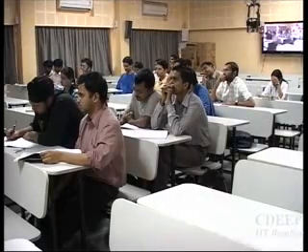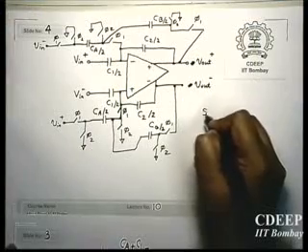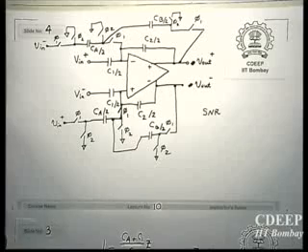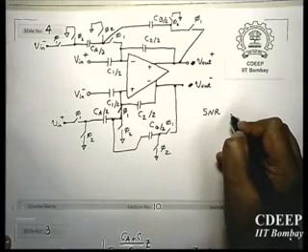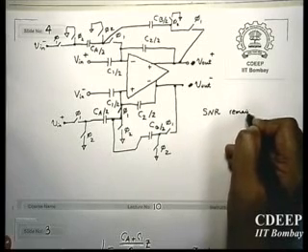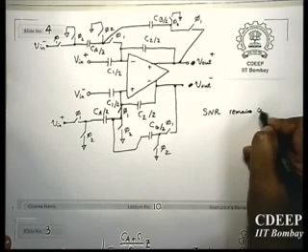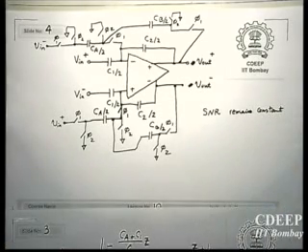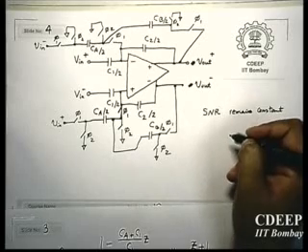So what we do here is keep the SNR, assuming that the contribution of the op-amp to the noise has not changed, therefore SNR remains almost constant. By just making the capacitors smaller, we save area.